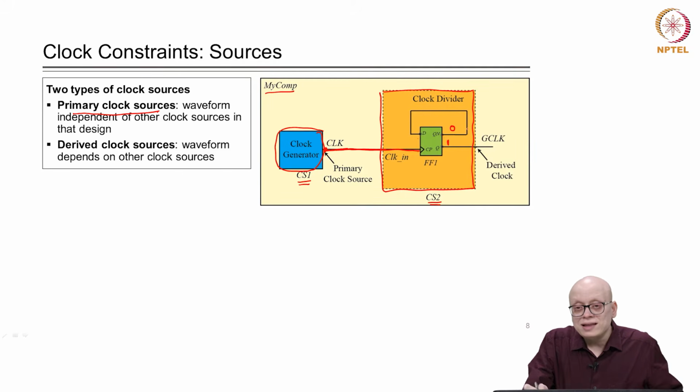Whenever the next clock edge comes, D will take a value, since D is 0, the Q output will take a value of 0. Now, since Q is 0, Qn will be 1. So in the next clock edge, it will take a value of 1. So the Q pin here will be taking a value of 1, 0, 1, 0 whenever the clock edge comes.